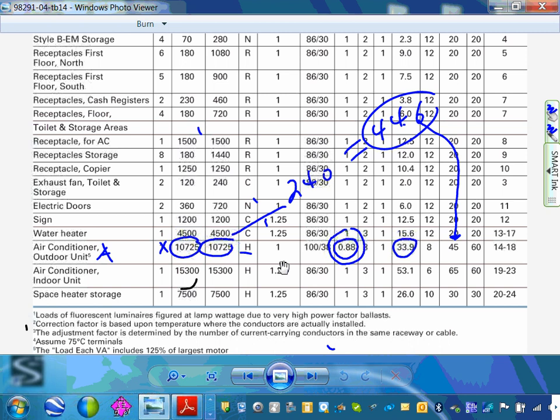Right, okay. Now, go size a conductor for 45 amps on the 60-degree column. That will get you this number. Number 6 or number 8? Number 6. That's why you guys are corrected. Number 8 is rated 40.